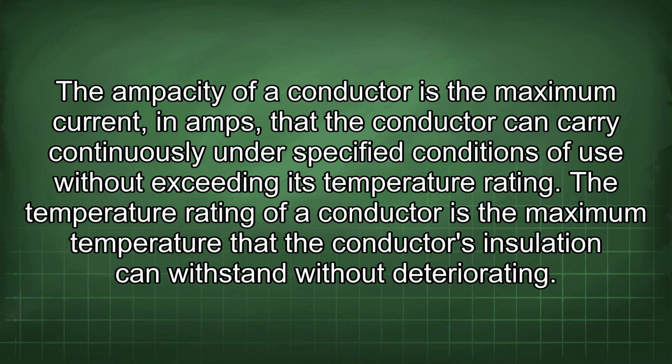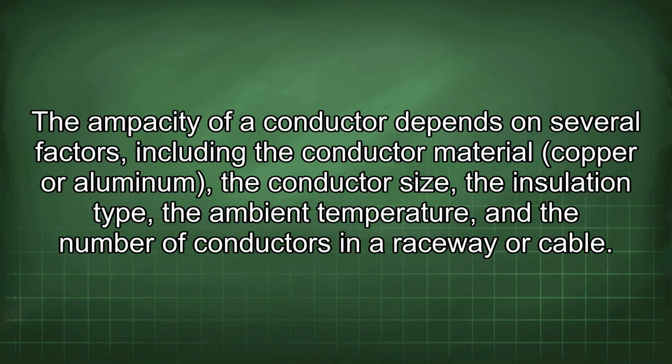The temperature rating of a conductor is the maximum temperature that the conductor's insulation can withstand without deteriorating. The ampacity of a conductor depends on several factors, including the conductor material, copper or aluminum, the conductor size, the insulation type, the ambient temperature, and the number of conductors in a raceway or cable.